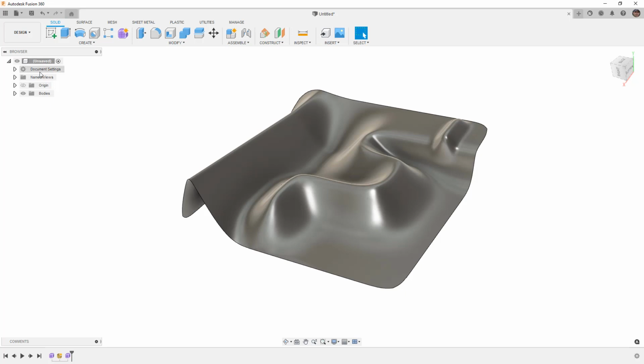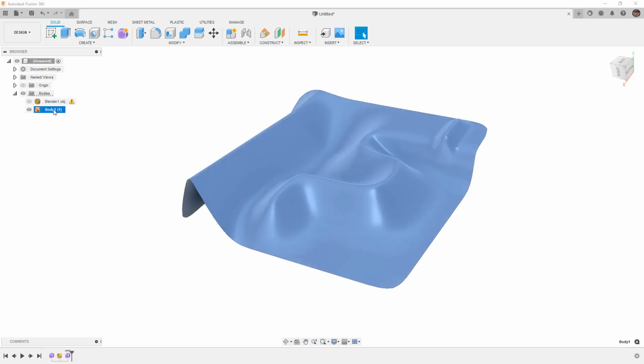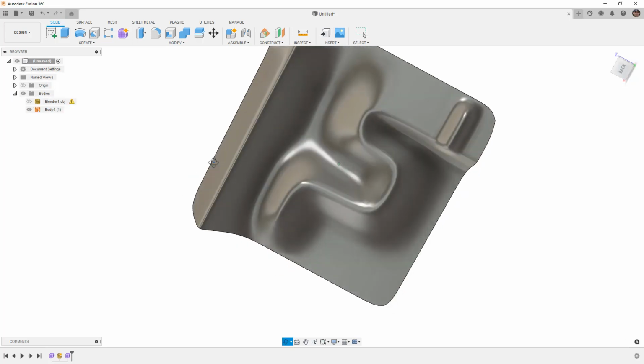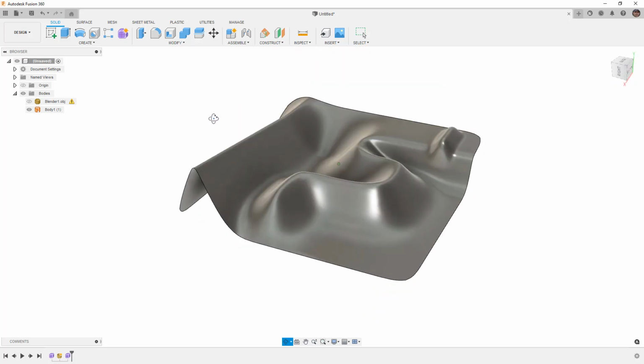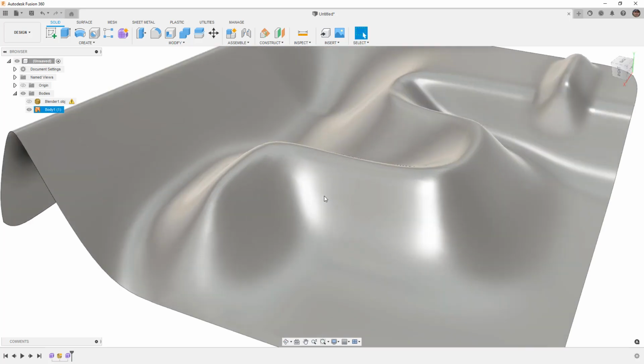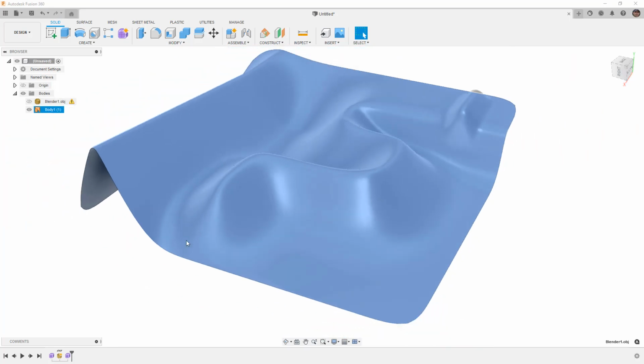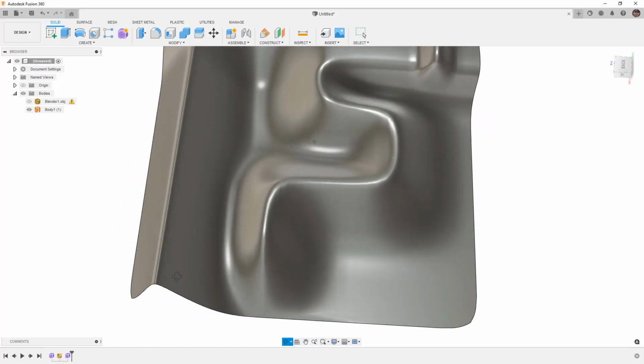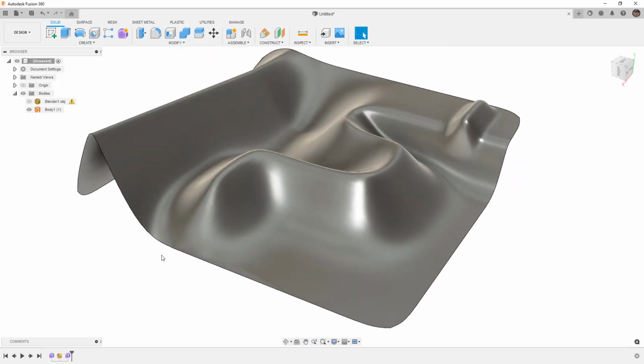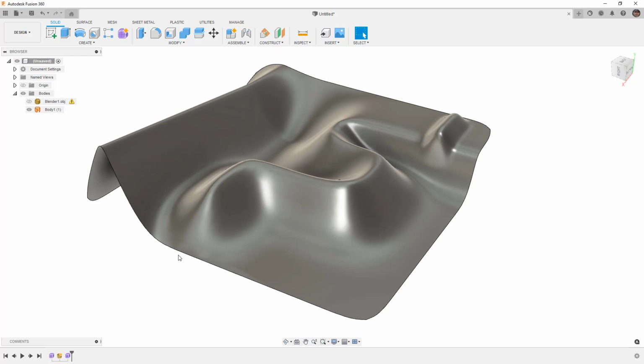So if I finish the form, I've now taken what I've done in Blender and I've converted it to a true B-rep surface. Taken everything, and the level of detail that we have in the quad mesh, has been converted to a form, and that form has been converted to a surface. And of course, it is still editable. So this is a great workflow that we can consider when we're trying to make these organic shapes, or things that just might be a little bit easier for us to define as a mesh body than as a surface